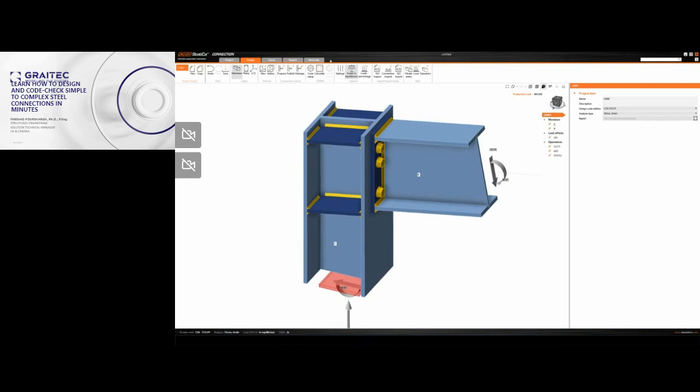Here on top, as you see, we have all of our tools to create our models, apply our loads, add operations or models. And we are in the Design tab, actually. The Design tab is the place where you will create the geometry. After that, we will move on to the Check tab to check the results and create our reports. Finally, we also have another tab here, which is called Materials. In case of adding new customized material or customized bolts or anchors, etc., you can go there and add your customized elements. So just to show you an overview of what kind of tools we have here.